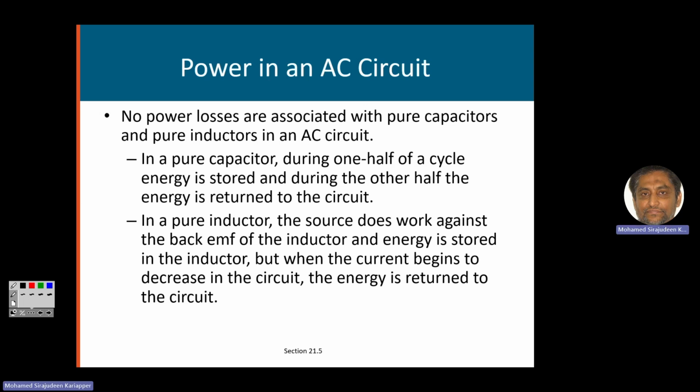So what happens in a pure capacitor? During one half of the cycle, energy is stored in the capacitor. It is connected to an AC source, so you know the current changes, the value changes. So one half of the energy is stored in the capacitor. In the other half, the energy is returned to the circuit as the charge is lost from the capacitor. Then it gives back to the circuit.